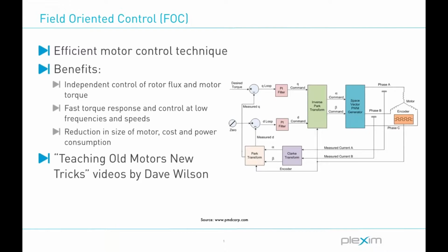For those of you who may not be familiar with field-oriented control, or FOC, it is a high-performance motor control technique that is quite attractive for many different applications. As you can tell from the name, FOC involves controlling the orientation of a motor's fields to achieve a desired result, which is keeping the net stator current vector at 90 degrees with regards to the rotor flux axis to achieve the maximum torque per amp.